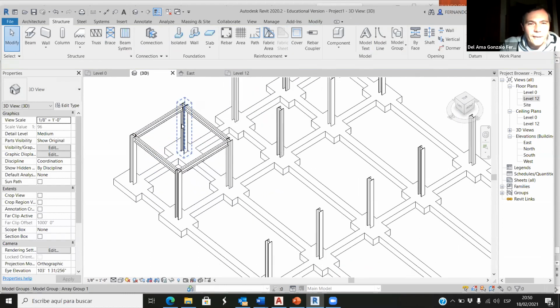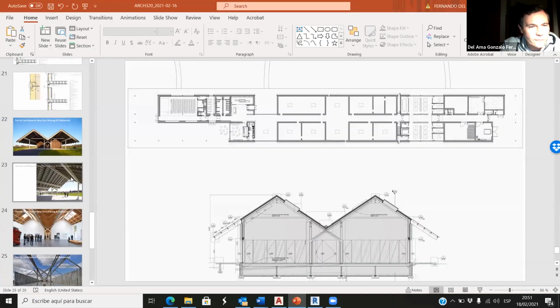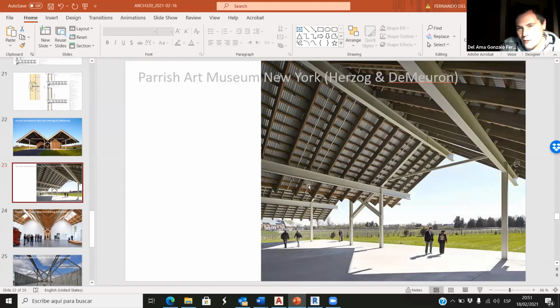Keep that in mind. Now I want to show you something different because we have this and 12 by 12 is too large for slab. So we need secondary structural elements. And again, I show you what the masters are doing. We see that we have those large beams with a long span. Then we have another order of beams that are resting on this beam and that beam. And then we have smaller beams. Those are beam systems that have this short span in this direction.